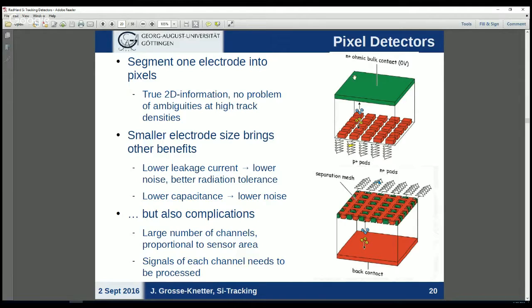Since you do some doping on that side anyway, you might as well segment that. But now the problem that I mentioned before comes into play. That would be short-circuited because, in that example, you would have N doping on N bulk. There is no automatic PN junction, so you have to add it manually. Typically you apply an extra P doping between your pixel electrodes, but then you can also segment the opposite side. That's an interesting feature. Again, please keep in mind, it comes back later.